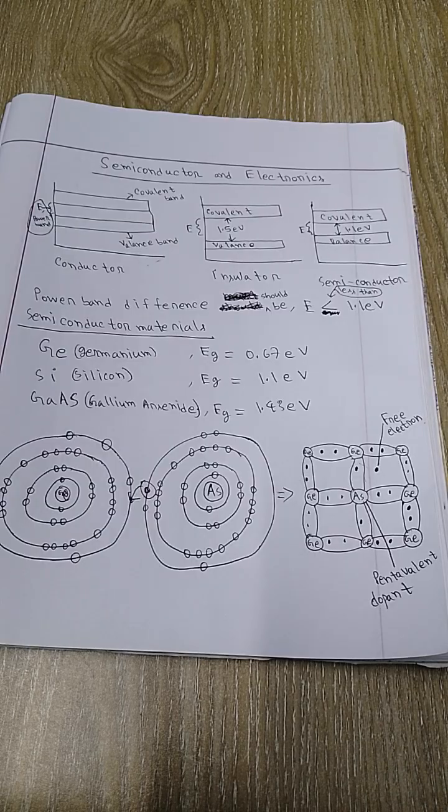This process is called doping. We have to add impurities at that stage. After doping, the semiconductor becomes an extrinsic semiconductor. Extrinsic semiconductors are of two types, n-type and p-type. N-type semiconductors are doped with pentavalent atoms such as phosphorus, and extra electrons become majority carriers. Then p-type semiconductors are doped with trivalent atoms such as boron, and holes are majority carriers.